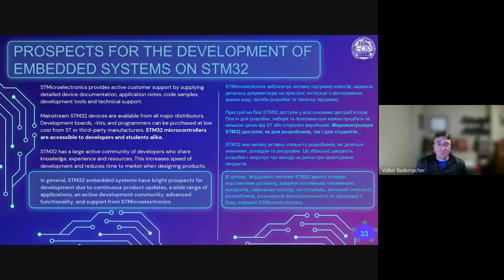So if you encounter a mysterious bug that only happens occasionally, the first thing that you can do is read the errata sheet and make sure that it's not a problem with the silicon, like with the chip itself. It happens, like every processor has errata sheets. Every processor has little tiny issues that may or may not be important. But yeah, for that reason, good documentation is important.